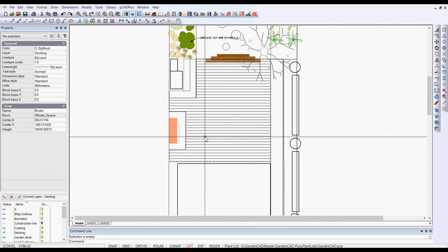So hopefully that leads on from our discussion of line weights. Now we know how to set a pattern for a line. So you might set different patterns for boundary lines and for hidden lines within a drawing. And certainly if you've got special fence lines or gas utility lines and so on, you can use a line type pattern to show that.